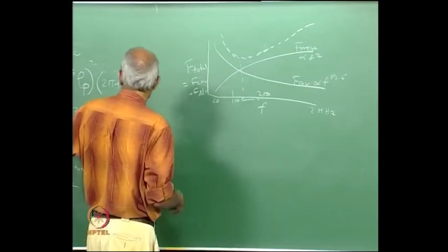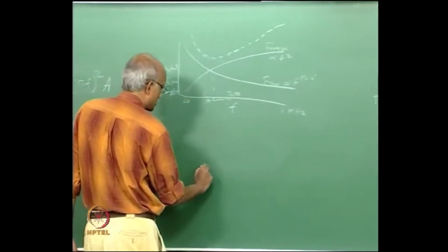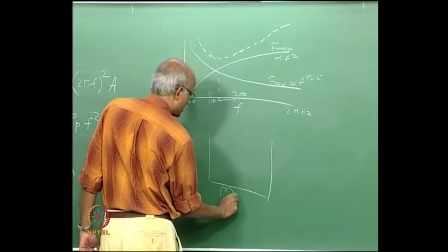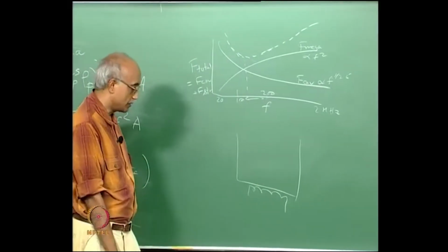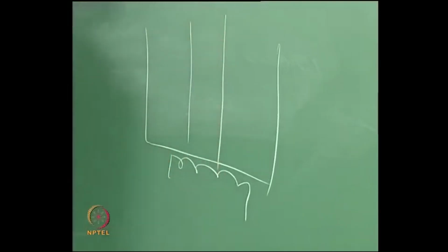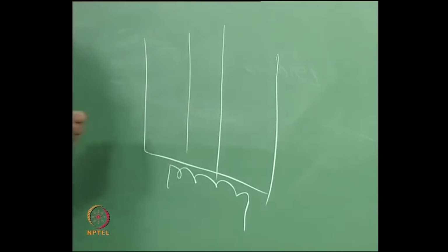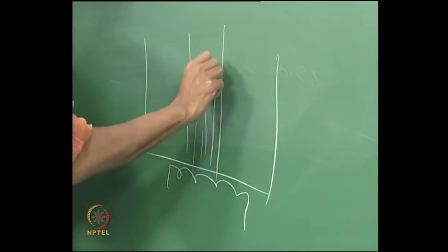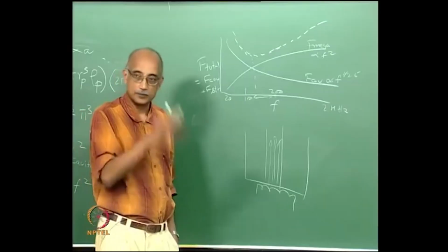In megasonics, this force that we are talking about, the F megasonic, only applies in a normal direction. For example, if you have a megasonic tank and you have your transducer mounted at the bottom, the megasonic field that you get is essentially a plane that is centered around the transducer. So, all the forces are only on top of the transducer and in one direction only.